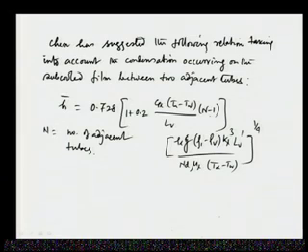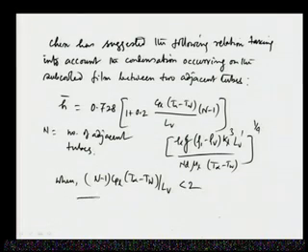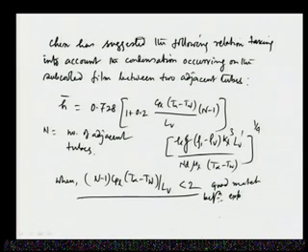Many times this L_V is replaced by L_V dashed, and by replacing it with L_V dashed it gives sufficiently good results. It has been found that this relationship gives a good match between experimental and predicted values when (n minus 1) into C_PL into (T infinity minus T_W) by L_V is less than 2.